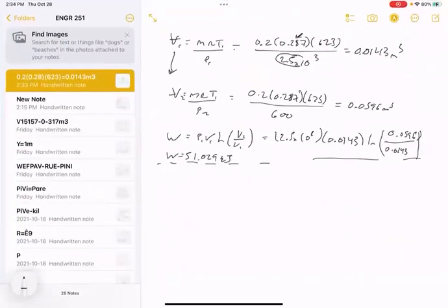So now, and for those who don't remember, a polytropic process is basically defined by the relation PV to the N is constant. So that means that P1 V1 to the N, in this case, because we're going, so this is state 1 to 2. Now we're going state 2 to 3. So P1 V1 to the N, and they're telling us that N is 1.2, is P2 V2 to the N. Sorry, these should be 2s and 3s. So P2 V2, we know from the first question. So it connects back. So this is V2, and P2 is given to us as 600, right?